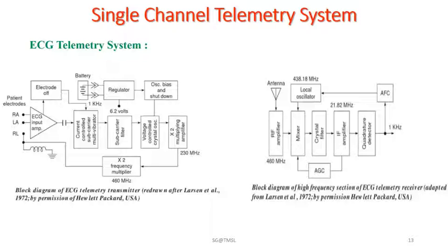A subcarrier oscillator must be there, where a current control multivibrator circuit can be used to provide some deviation of the signal. A subcarrier filter must also be there to remove the square wave harmonics, which results in a sinusoid for modulating the carrier signal.